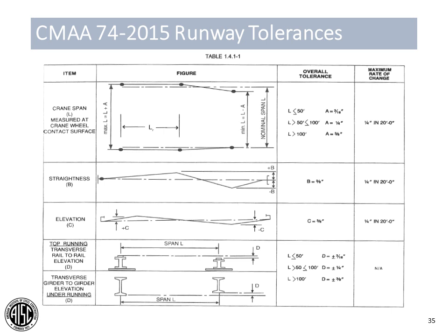I have seen some details where you can provide almost a pivot piece at a building expansion joint. You preset the detail basically based on these CMAA tolerances, and that will allow the building to expand one way or another and maintain the continuous runway itself.